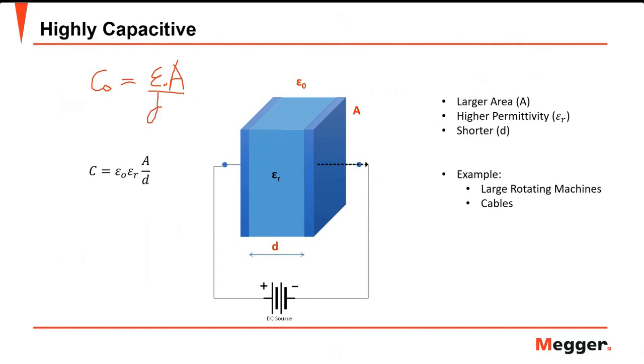And this is very useful to get the capacitance value. In most cases with insulation resistance testing, you can also check the capacitance value. Maybe later on, or in the next webinar, I will discuss how to measure the capacitance using insulation resistance testing. It is very important to look at the geometrical capacitance, because this will indicate if you have some deformation in your insulation.